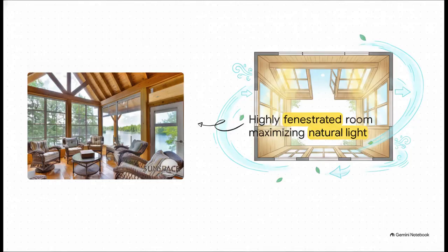This beautiful interior shows off intelligent fenestration perfectly. The location of your windows must be determined by looking at the prevailing wind direction of the site. By strategically positioning large windows on opposite walls from one another, the design drastically increases natural cross-ventilation. At the exact same time, it floods that optimized building depth we talked about earlier with natural daylight, almost entirely wiping out the need to flip on a light switch during the day.